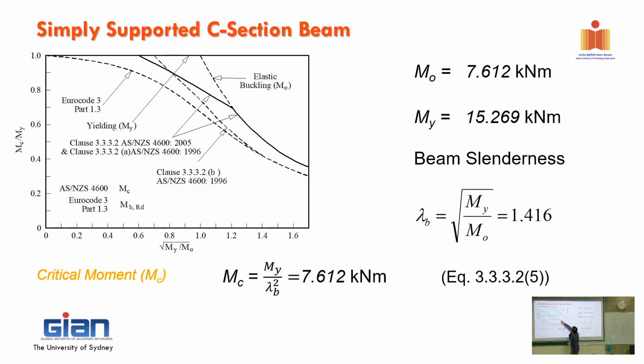So you can see the code telling you from 1 to here. It means that you have fully restrained your beam, like you put five restraints, all right? So then, no problem with the member. It's just section capacity. But if you remove more and provide less lateral restraint, then strength can drop down because of the member capacity. It can buckle sideways and twist.